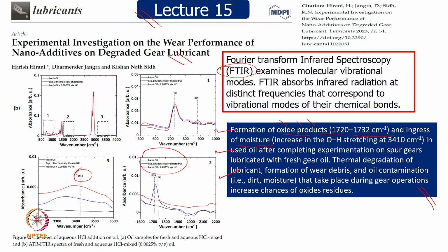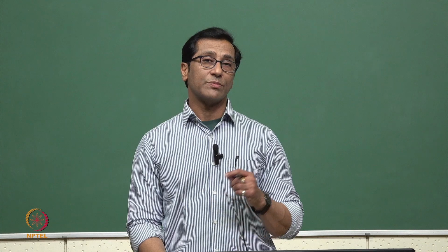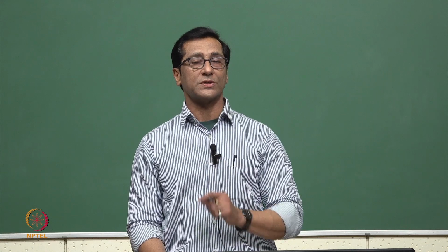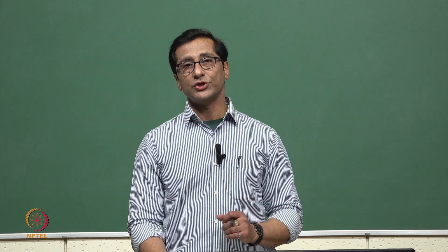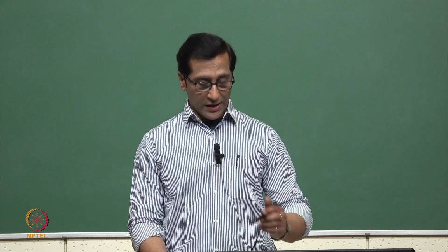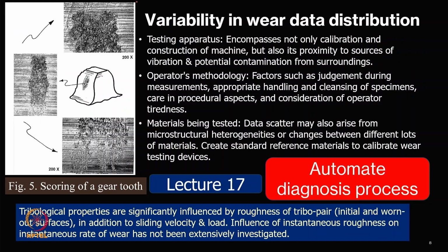and based on the pH level we can predict what will be the quality of the lubricant, and if bad quality is happening, what is the reason behind that. We can analyze it, and then we can schedule the maintenance accordingly. And this was covered in lecture 15.